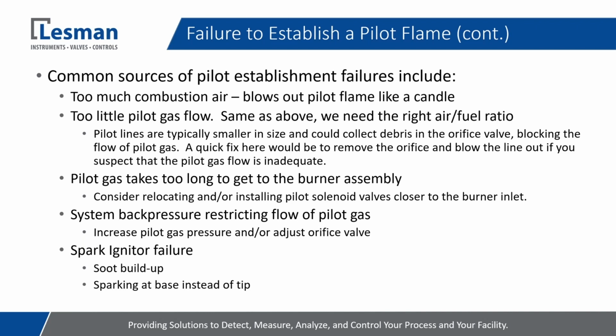Another issue that I've seen is that if you've got a spark igniter that's got a little bit of a tip on there, I've seen it sometimes where, because of either an improper installation or just a failed spark igniter, it's arcing at the base instead of the tip of the igniter. So that's something that you want to be mindful of, and I highly recommend that everybody has at least a spare spark igniter on hand, because that's one of the showstoppers, right?